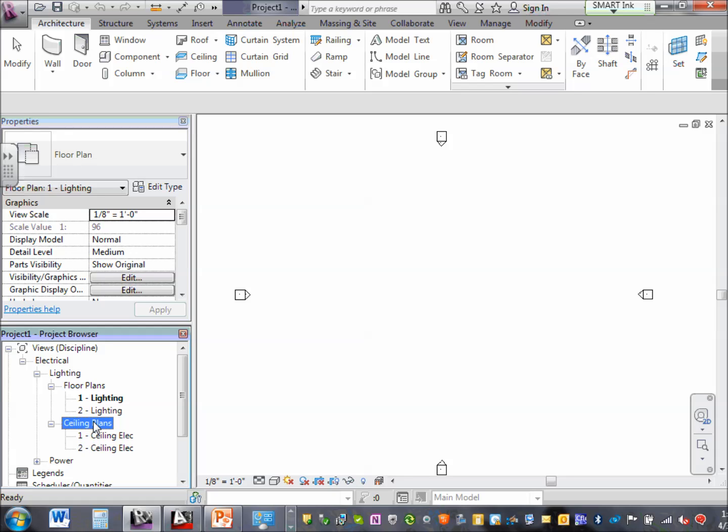Why? Because when you drop it, it defaults to 18 inches above the floor and puts it somewhere right here. If you don't like it, you can elevate it, take it up and down. Another thing, when we drop switches, we do it in the floor plan. You don't put it in the ceiling, you put it in the floor plan. Floor plan means in the floor or slightly above the floor, up to typically 4 feet. It automatically defaults to the level it should be.